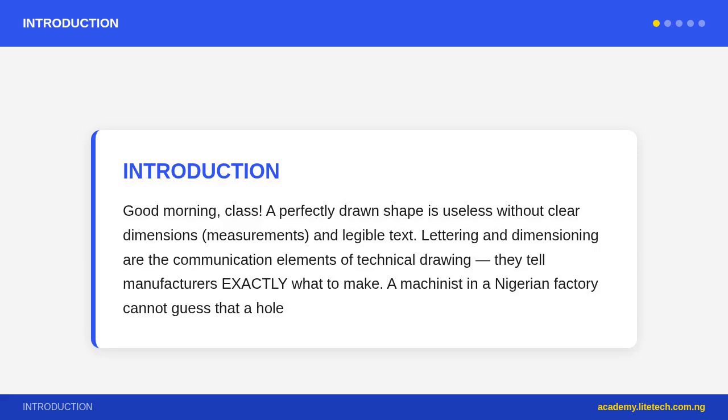ISO 3098 lettering standard. Height, H: main titles and drawing numbers typically 5 to 7 mm, notes and dimensions typically 3.5 to 5 mm. Line thickness, 0.35 mm for lettering on a drawing with 0.5 mm outlines. Spacing: between letters is almost equal to 0.2 h, between words almost equal to 0.6 h, between lines almost equal to 1.6 h.